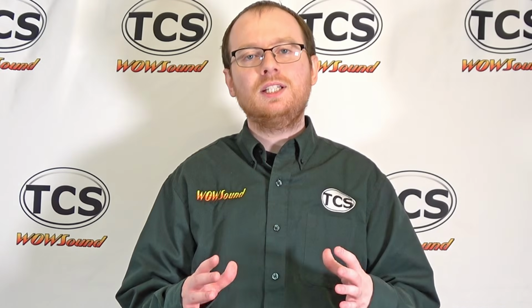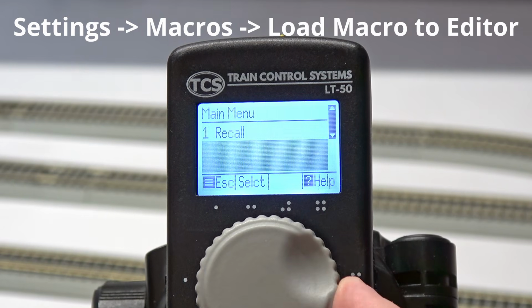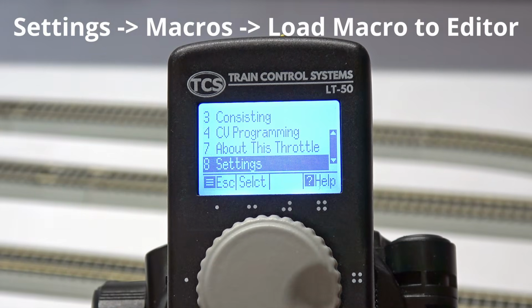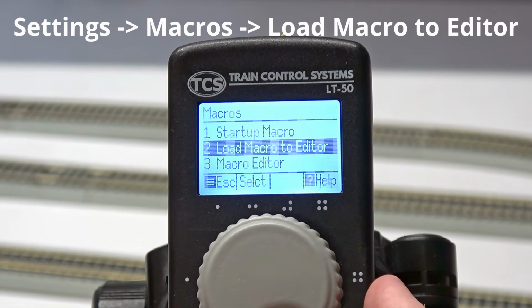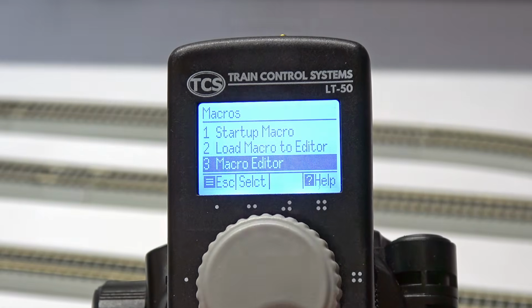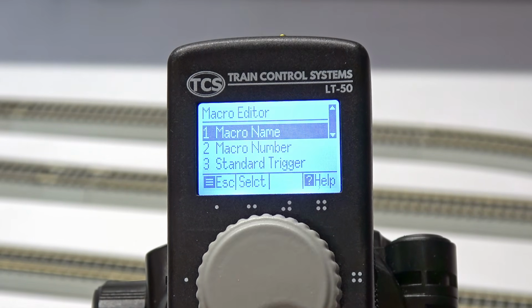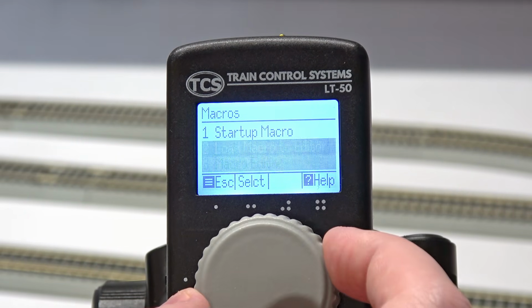The LT-50 has a built-in tool for setting up and creating macros. To create a macro using the built-in editor, first go to Settings, Macros, Load Macro to Editor. Create a new macro by assigning a number 1 through 20 using the keypad or scroll wheel. Press the 2-dot button to create and save the new macro. Once created, you will be back in the Settings Macros menu.